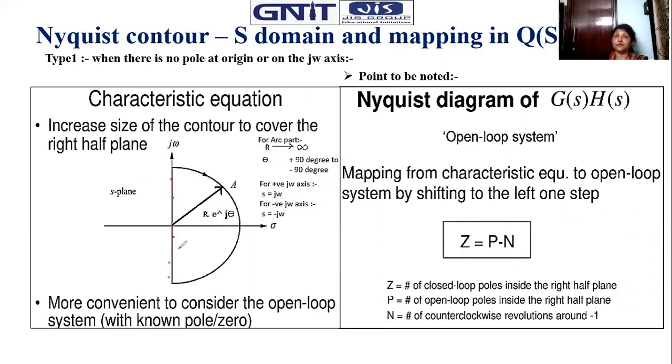And now regarding the Nyquist criterion. How do we apply the Nyquist criterion to a specific problem? Then we have to understand, because while dealing with certain numericals, you have to find the concept. First of all, what is the first step? The first step is the PZ map. From the PZ map, you find the number of poles that exist at the right hand side.